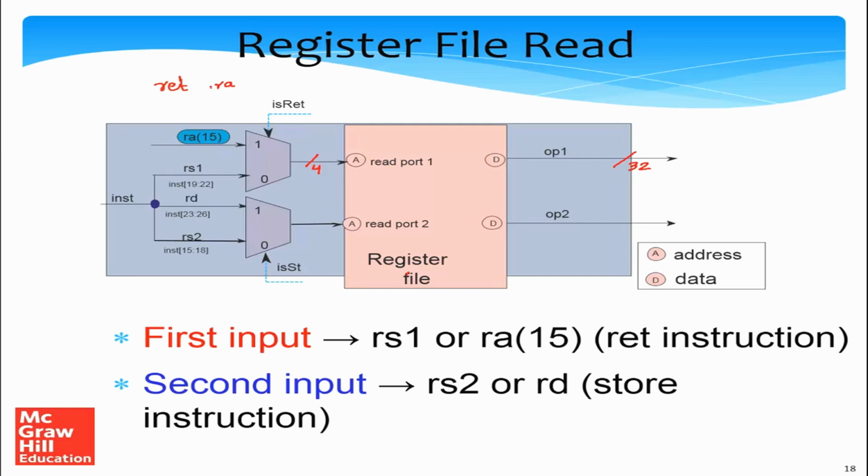The contents of register RA are transferred to the PC. Whatever address is stored inside the return address register becomes the contents of the program counter in the next cycle. In effect, the function returns and goes back to the instruction just after the call instruction.